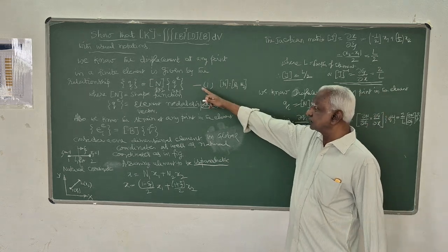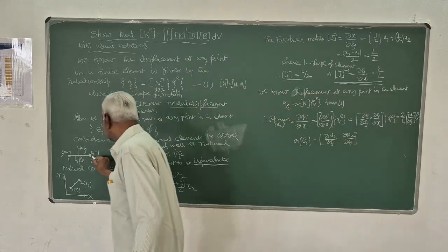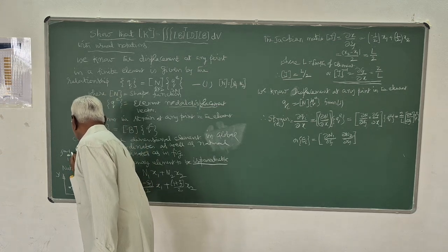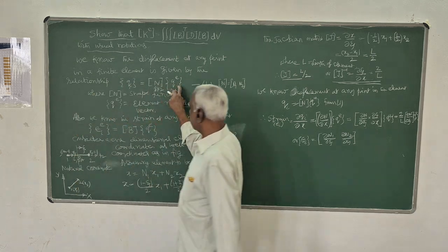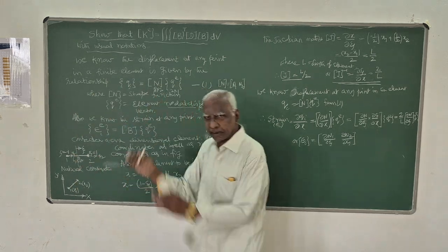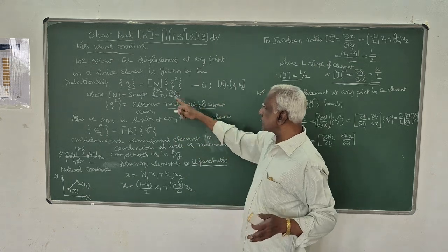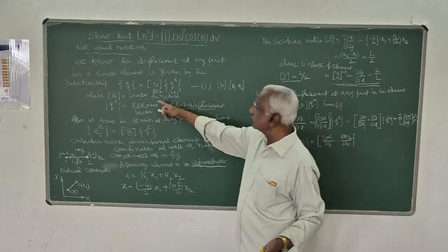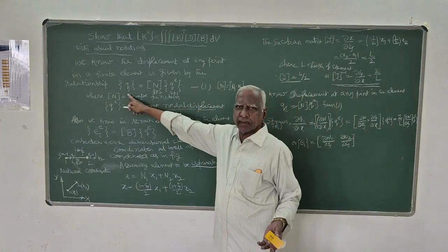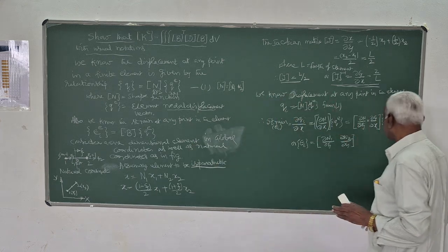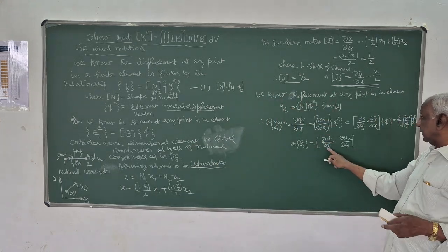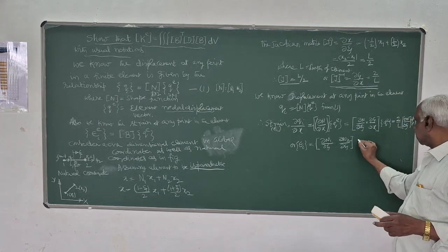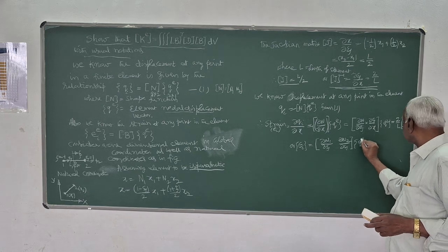Q is nothing but Q1 and Q2, displacement at 2, displacement at 1. So this QE is nothing but the Q1, Q2 vector. That is a 2 by 1 matrix. N is the N1, N2 matrix. So you can multiply it easily. So this will be a 1 by 1 matrix, that is Q, displacement at any point. So N is N1, N2. Here delta n by delta xi is given by this into QE.